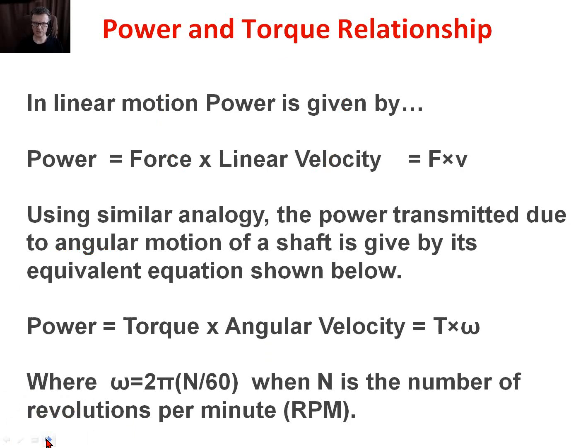Why am I interested in torque? Well, torque relates to the power that a particular shaft can transmit. If you think of submarines or helicopters or aircraft, these will all have a certain amount of power that they're trying to transmit down the shaft, and that's going to relate to the amount of torque it can experience times its angular velocity. So that is T times angular velocity, where angular velocity there is in rads per second. So you need to watch out that your angular velocity is not in RPM, in which case you need to convert it by multiplying by 2 pi, remembering a revolution is 2 pi, and dividing by 60. So per minute then becomes per second.